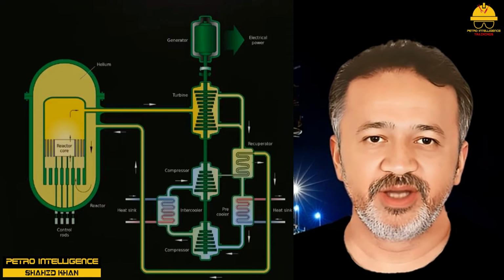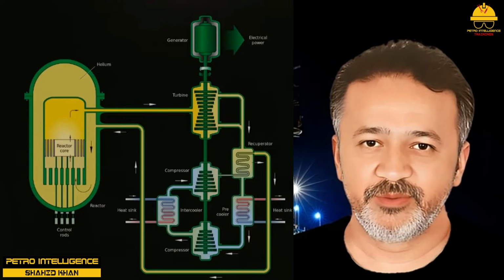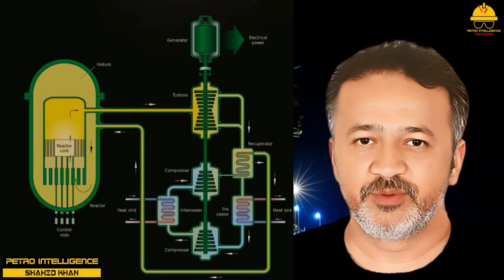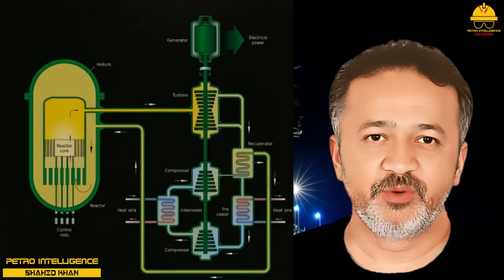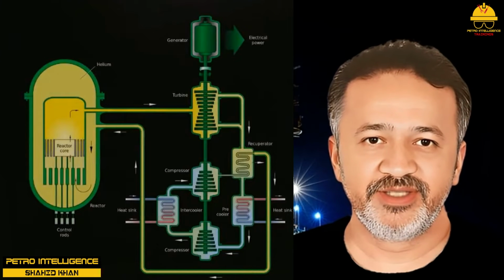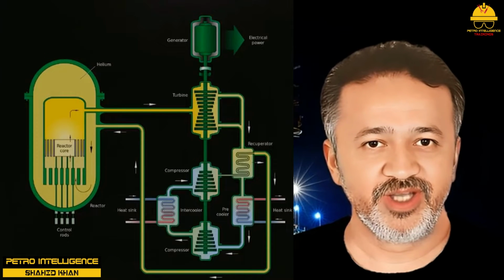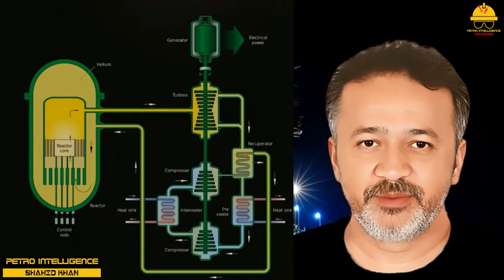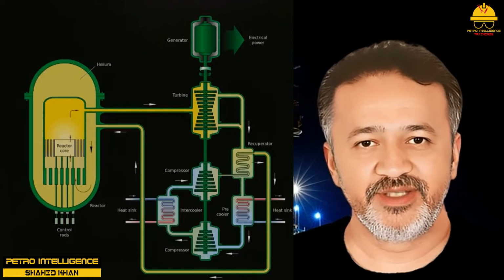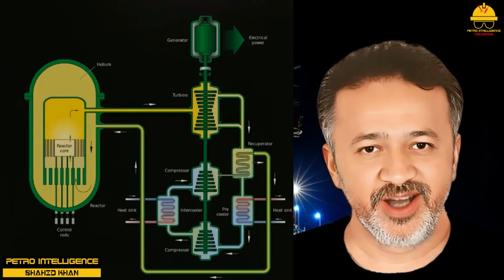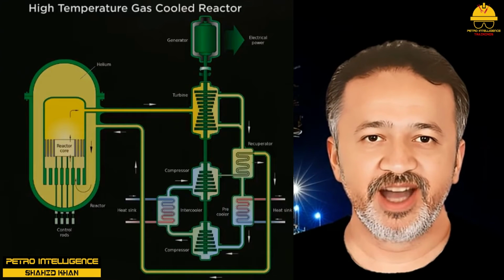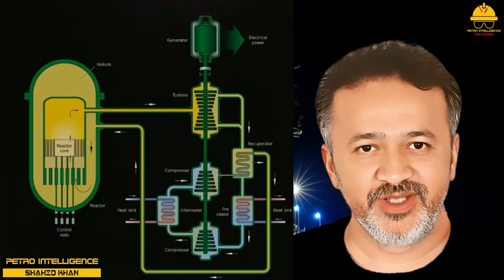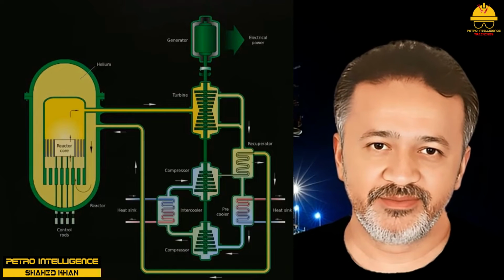For example, if 10% of the chemicals in a reaction form product in 1 hour at 50 degrees Celsius, then 20% will form products at 60 degrees Celsius in 1 hour. The danger in this type of reaction is that twice as much heat will be given off at the higher temperature. If the extra heat cannot be removed from the reactor as fast as it is formed, the temperature will rise, causing the reaction to proceed at even higher rates. Obviously, you will soon have an uncontrollable reaction and, possibly, an explosion.